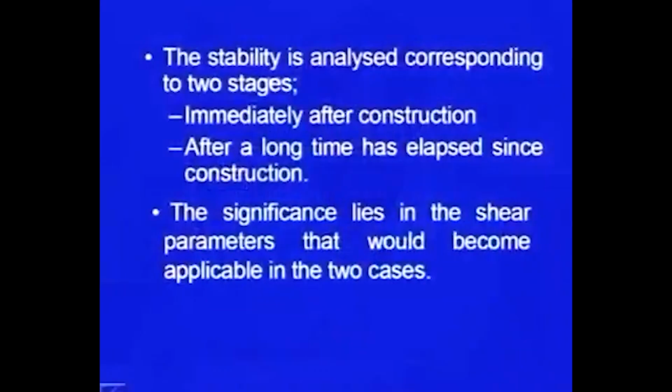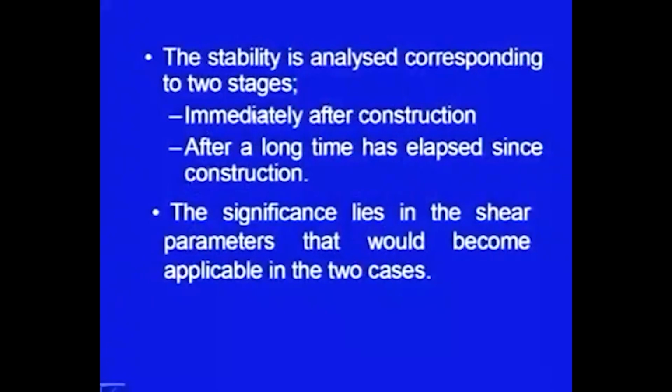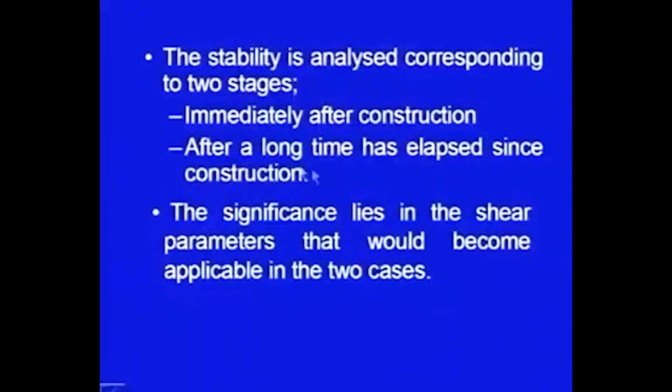The stability is analyzed corresponding to two stages. This is specifically for man-made structures, for embankments, for dams, earthen dams or rock-filled dams. We generally consider two extreme cases. First is immediately after the construction. Just after the construction has been completed, at the end of the construction, we analyze the situation. And second is after a long time has elapsed since construction.